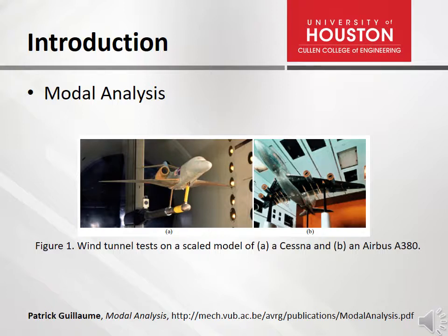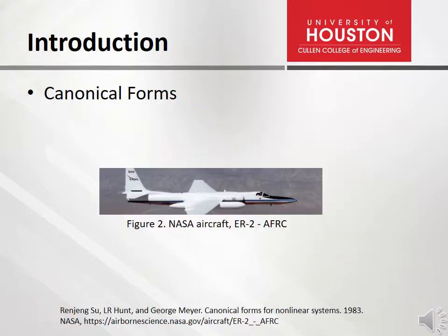The damping values are then extrapolated in order to determine whether it is safe to proceed to the next flight test point. Flutter will occur when one of the damping values tends to become negative. Before starting the flight tests, ground vibration tests, as well as numerical simulations and wind tunnel tests, are used to get some prior insight into the problem, which is shown in this figure.